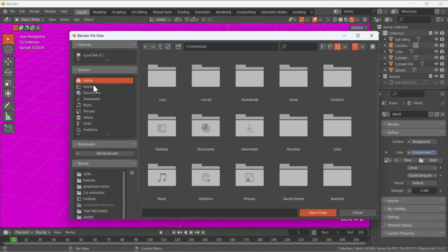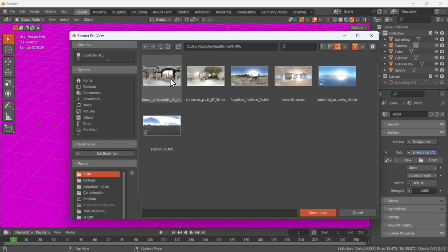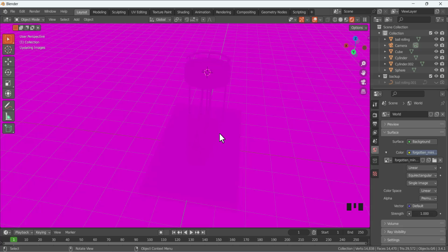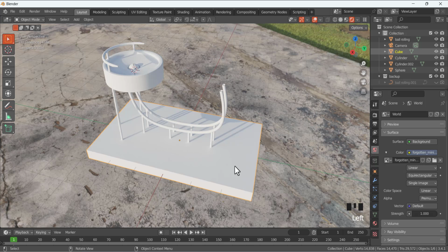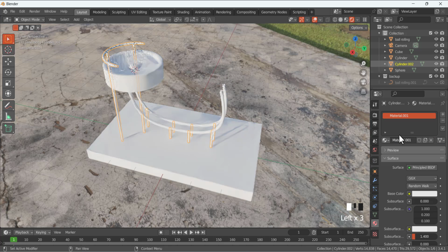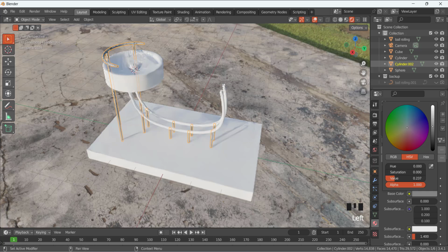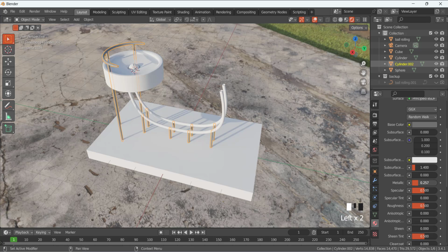Okay, now we are going to add the material for this object. So select this and I am going to add the texture for this object. First select this one, go to material and add new material and I'm going to name it metal. Spellings of guys, metal. And for the surface Principled BSDF make it a little bit gray, then metallic, and for the roughness like that, something very shiny. And select this wire also, apply the same material. For this base, I'm going to add a wood texture and also the same texture for the front.